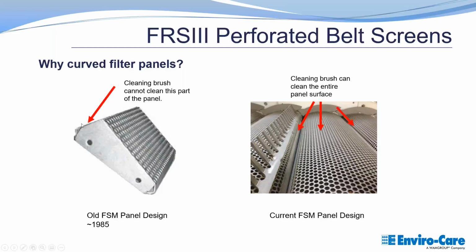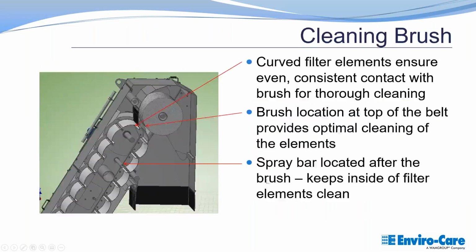But it also makes it very hard to clean inside this crevice in here. So you get a lot of debris that would sit in there until it comes around, and then the force of the water going through the channel brings it out, which then creates a condition called carryover, where you could lose that material that you've caught once, carried over, and then let go downstream. It's not very ideal. So this is where the panel design has been improved. Go to a curve style design. One of the big advantages of the curve style design is as the panels come up and around, you have a sprocket in here.